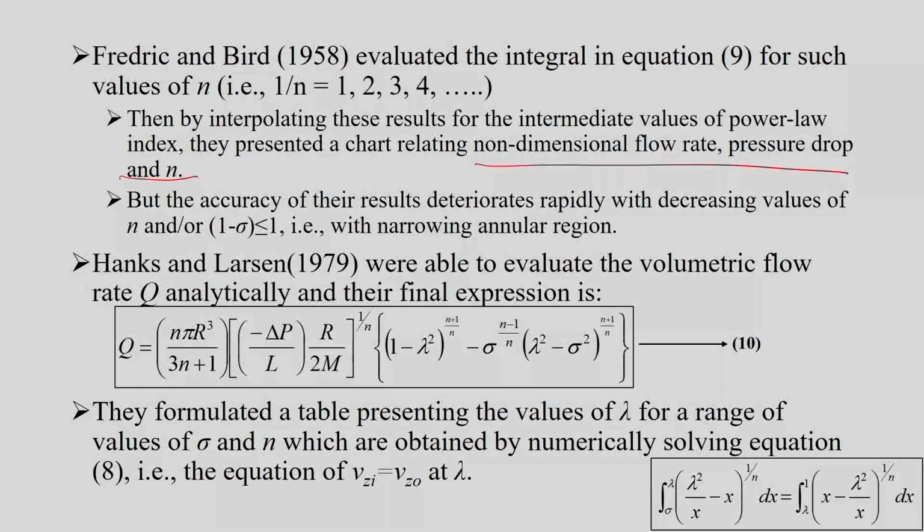However, their results found that the accuracy of those results deteriorates rapidly with decreasing power law index, that is, increasing shear thinning behavior, or when the channel becomes more and more narrow. In either case, the reliability of the Fredrickson and Bird solution, the accuracy, is deteriorating.